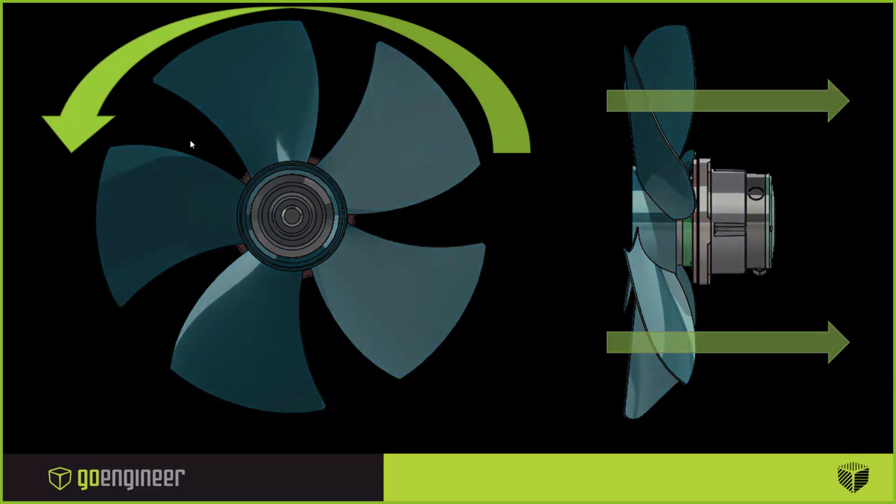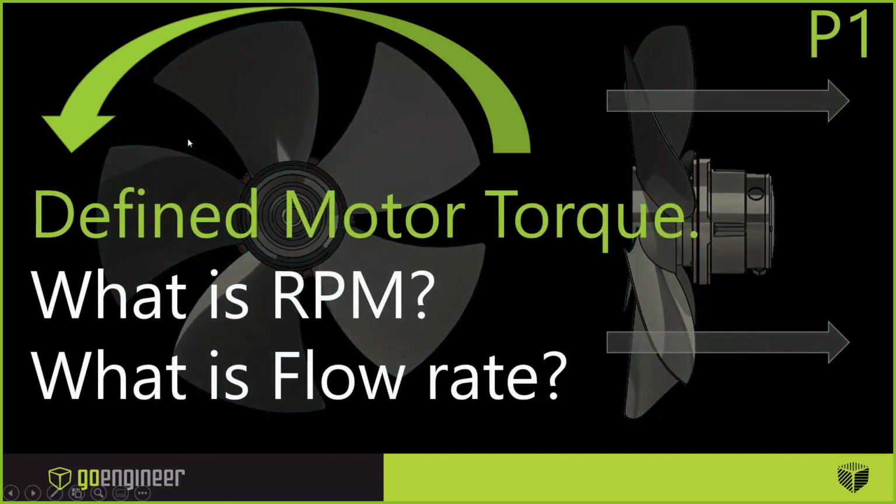So starting with our first setup. For problem 1, we will introduce the overall flow simulation setup and guidelines, while saying, I know what the motor torque is. I know the motor torque I'm applying onto the fan. What RPM would that produce due to reaction forces like torque on the fan itself? What overall airspeed is produced by the fan rotating?